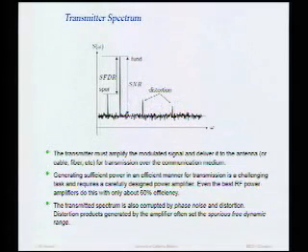So, of course, I can use filtering to get rid of these harmonics, right? That's not too bad, big deal. Build a little low-pass filter, you get rid of that. Well, as we'll learn in this class, distortion is not only generated at harmonic frequencies, but intermodulation and cross-modulation distortions are also created at our own frequency. So if the PA is very nonlinear, it will generate distortion in band, which will actually corrupt the signal that you're transmitting. And we'll learn how that happens later on in the course.